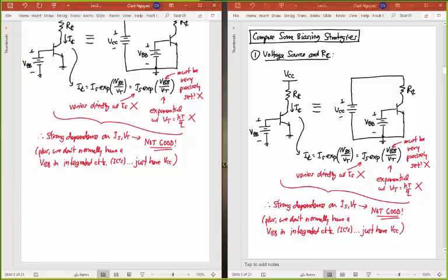as we work to a better circuit, and that is add a base resistor to VCC. Okay, so that circuit's going to look like this. I'm going to have a VCC. I'll have my collector resistor, my transistor, which will go to ground.